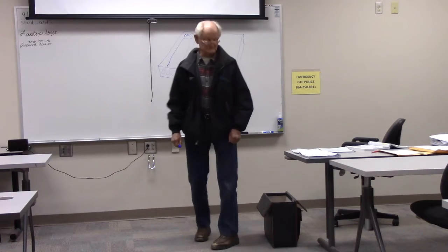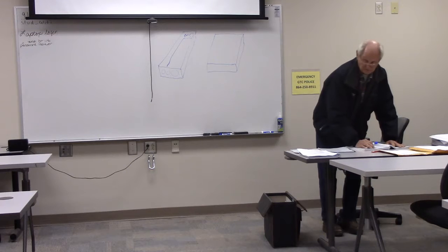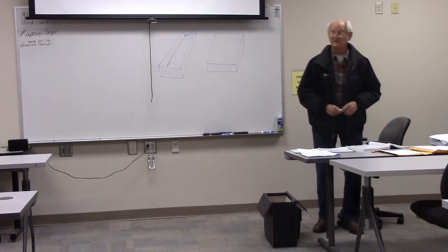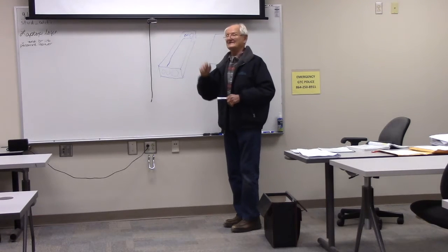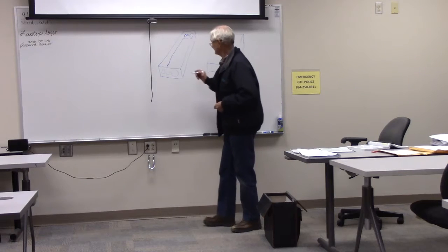Yeah, all right, what does it say? What do our rules say to us? 314.28, straight pull: the length of the box shall not be less than 8 times the trade diameter or metric designator of the largest raceway. All right, so we want to remember 8 times, and we want to know the diameter of the largest raceway.